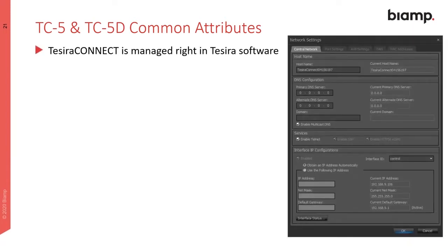Okay, so this is the dialog or the wizard in the network settings of the TesiraCONNECT. As you can see, in the control you can change the host name, and you can change the IP address of the control port or the media bridge port. If you have a separated network, if you need to separate the AVB and the control, then you have to be in the separated mode, which means enabling the AVB media in your TesiraCONNECT 5.